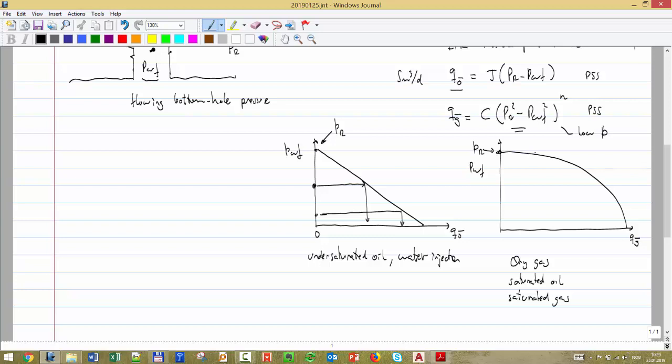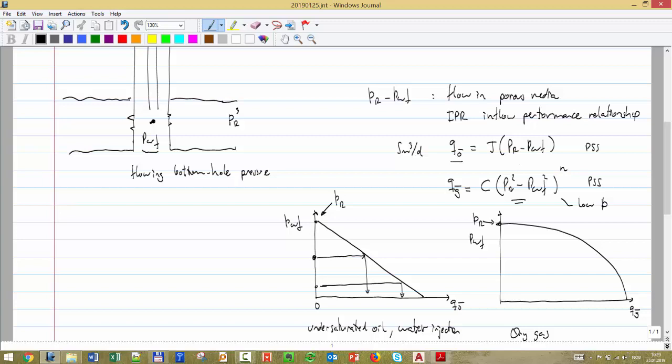And you can go to the literature, you can spend a month, a lifetime looking at different equations for all kinds of cases. Okay, horizontal well, vertical well, deviated well, slanted well, slightly light oil, heavy oil, all kinds of things. But you have to keep in mind two things. If time is not in the equation, pseudo steady state, I assume the transient is very fast and all the rest of the outtake happens at that regime, and no compressibility, a straight line. When there's some effect on pressure, you have a curve.